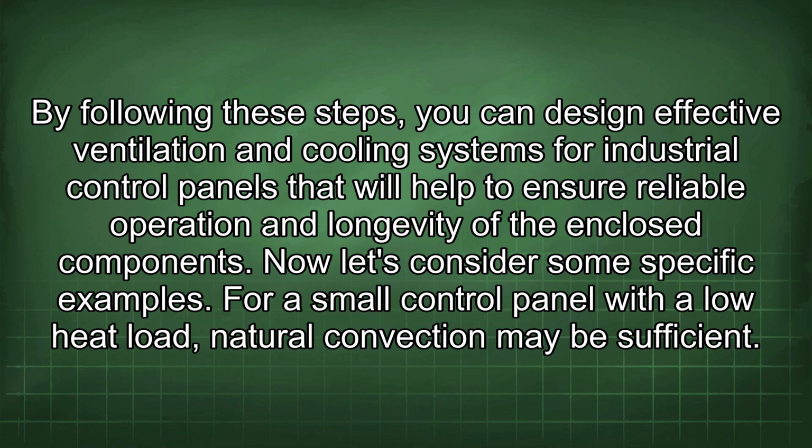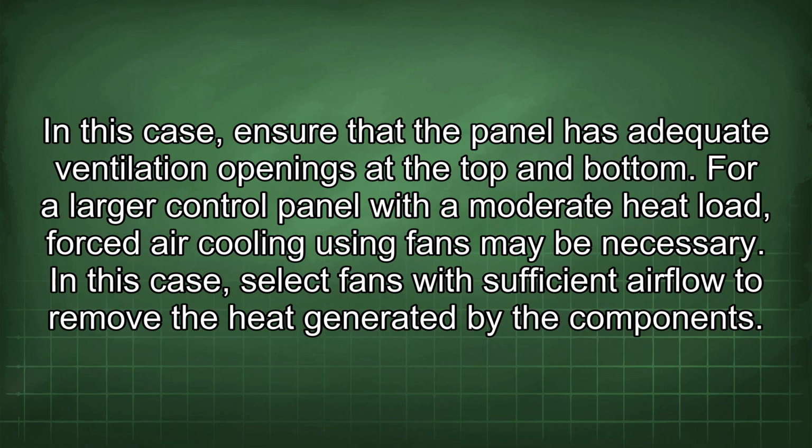Now let's consider some specific examples. For a small control panel with a low heat load, natural convection may be sufficient. In this case, ensure that the panel has adequate ventilation openings at the top and bottom. For a larger control panel with a moderate heat load, forced air cooling using fans may be necessary. In this case, select fans with sufficient airflow to remove the heat generated by the components.